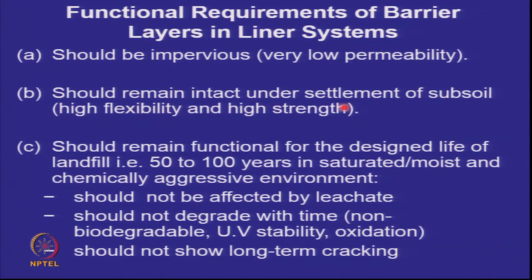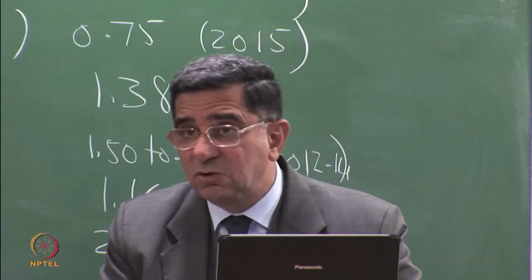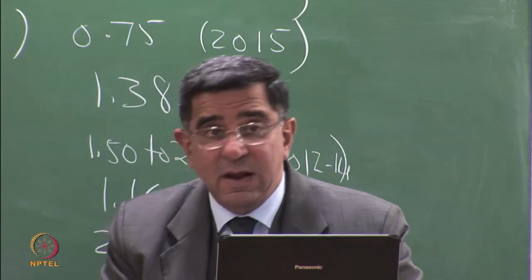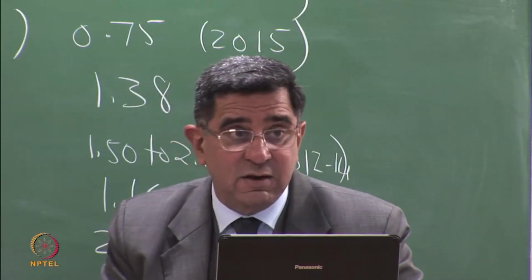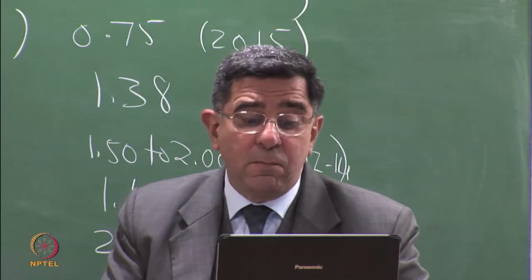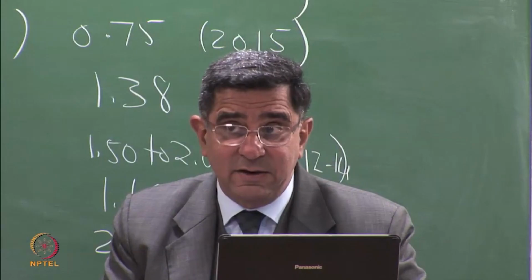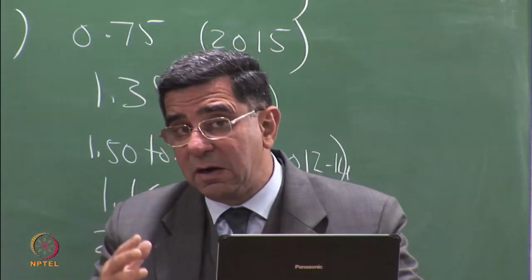And the other thing is that it should remain intact under settlement of subsoil. Now as you build up your waste, you're passing stresses onto the ground, the soil will settle a little, and therefore whatever you put at the bottom should not be a rigid element which will crack. This is more important in covers than in liners, because in the cover the waste itself is settling, so the settlements are much larger.